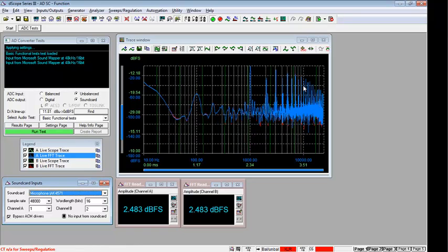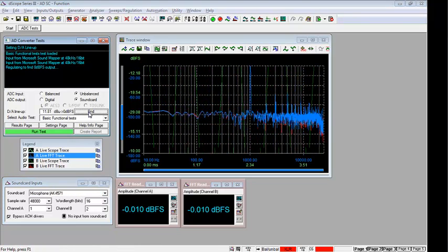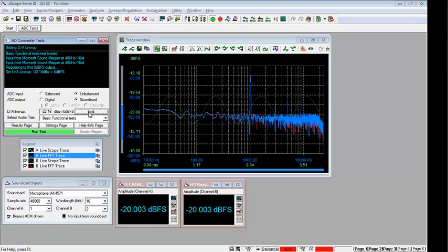Okay, that has now been completed, and you'll see straight away that we seem to have some rather excessive distortion in the digital output of this ADC converter. That's because it's designed to handle microphone level signals, and right now I'm generating a signal at quite a high amplitude for this device. So I need to find my DA lineup once again. So that's now happened automatically behind the scenes, and you can see now I've got significantly lower DA lineup than we had before. Minus 22.16 dBu of analog signal level will give 0 dB FS, 0 dB full scale digital output of this converter device.